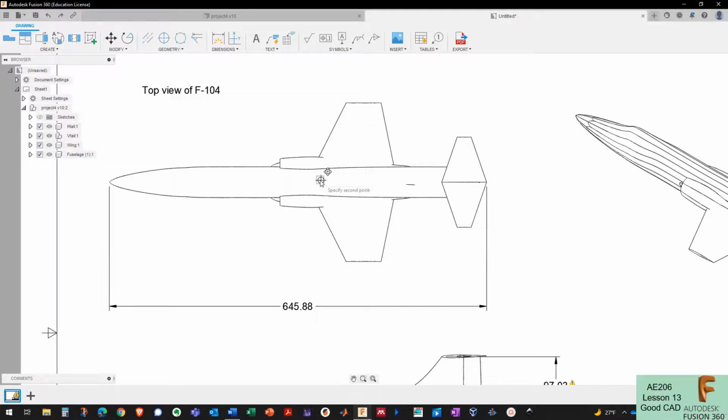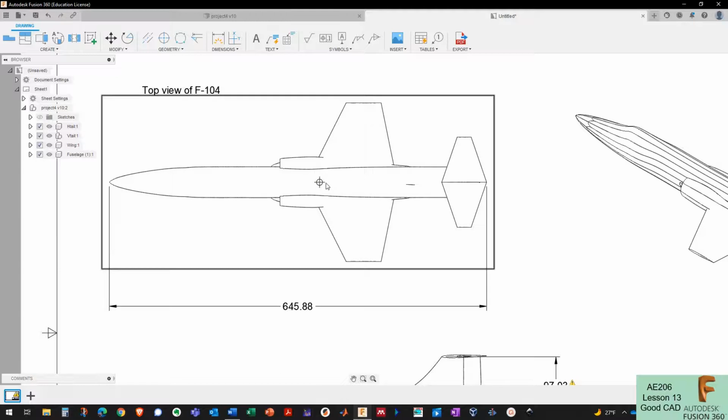The only other way to put in center of gravity exactly correctly is to go back to my object and draw something on a sketch plane, like a circle, at my exact center of gravity, extrude it a little bit, and then it'll show up here as a wireframe feature, and then I can dimension to that and call that my center of gravity.